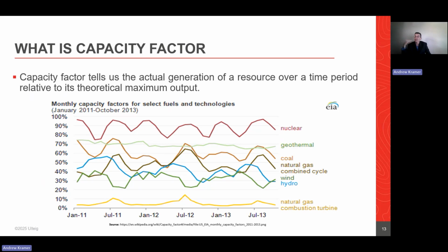If you do that, you're going to get to a point where the solar doesn't run at night. It still has an okay average capacity factor, but people don't like it when they go down at night and can't turn their light switches on, right? Or when their heating unit gives out in winter, or their air conditioner turns off in summer. Capacity factor is an incomplete view because it doesn't tell you the ability to match generation to load. That's why it's limited. It's an average information tool. And as I say, people in the United States don't like it when they go to turn their light switches on and can't get power out of them.